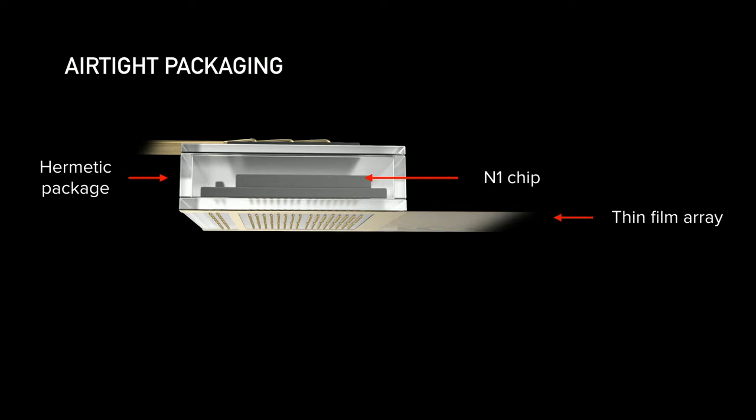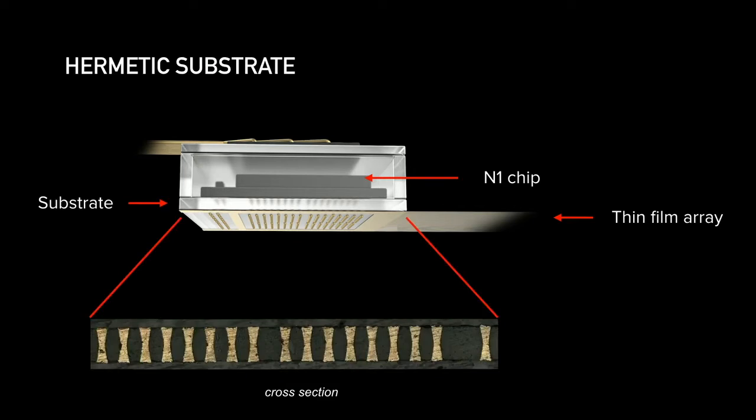Standard methods of connecting the probes to the electronics package usually involve some kind of large plug-in type connector or a polymer-based glue that bonds the two components together. But as we increase density and decrease the footprint, it becomes impossible to achieve hermeticity in standard medical device connectors. This is due to several reasons. One of them is how these substrates are currently manufactured. Hermetic feed-throughs consist of holes that have been packed with conductive materials and are embedded in an insulating substrate. As you drill more holes and pack them more tightly together, these brittle substrates, typically made of ceramics, become more susceptible to cracking. Also, as you make the holes smaller, it becomes more difficult to fill them with this conductive material without getting non-hermetic voids.